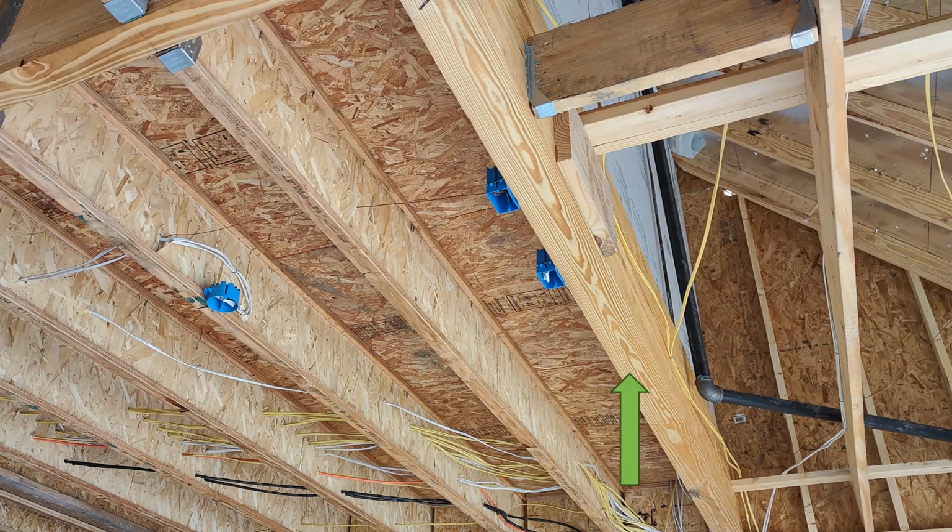We've seen it many a time where you're running a blower door and the carpet's still covered with plastic because it's being protected from damage. You run the blower door and the carpet lifts up off the floor. Yes, it lifts up because there's air movement through it, but it also could be just a pressure differential allowing air to go up.